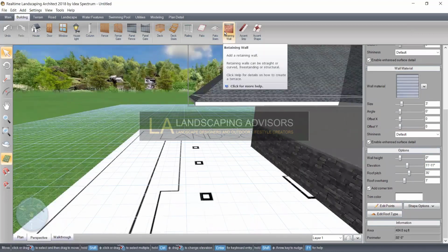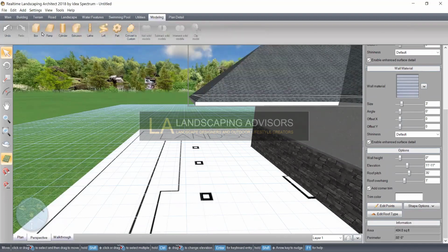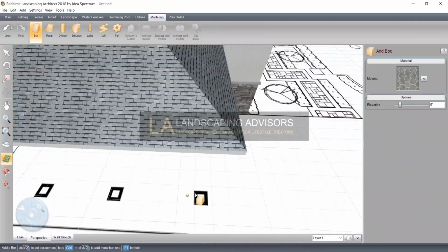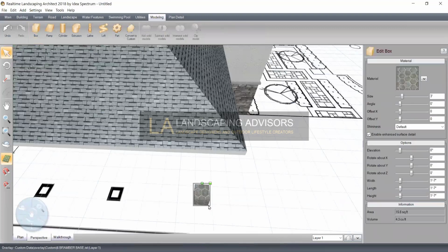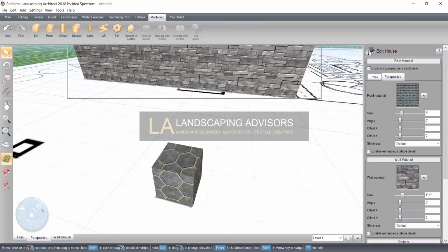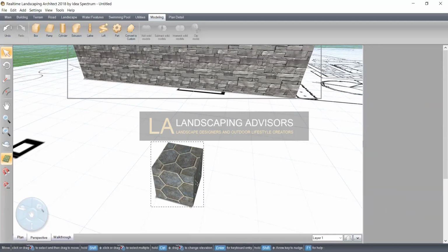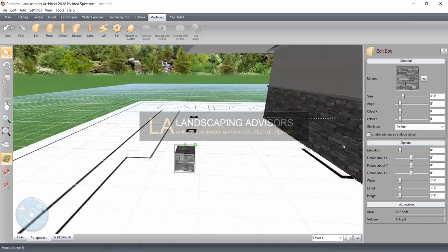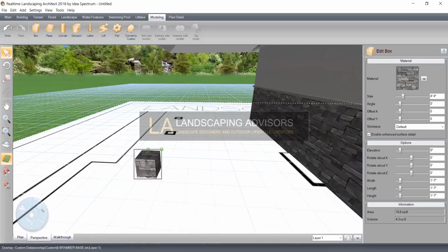And then we've got some pillars that we need to do. Usually what I do with pillars is I'll use the modeling tools. So you can go like that. And here's a little trick, you guys, I don't know if you know or not, but you can grab this and just go copy, and then you can go like that and paste it. So now you get the same color if you change the shade and all that kind of stuff. You get the same facing as the house to match the house. And then we're going to give this some height.